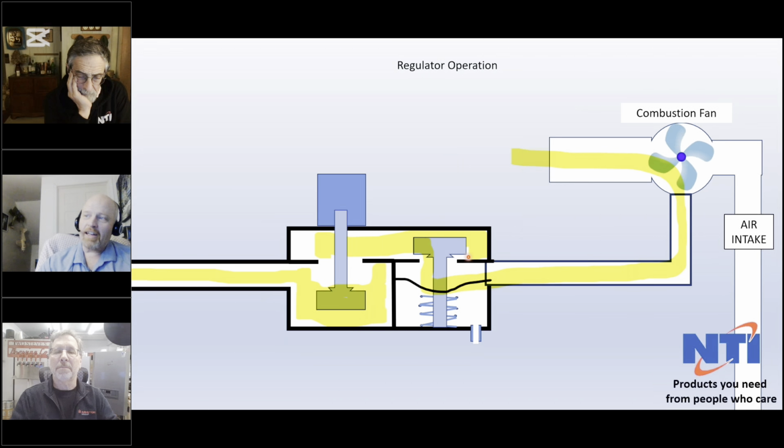topic. Again, our valve opens. And in a perfect world, what you're doing when you're setting the offset gas pressure, so you're going to make your adjustment to this regulator, you're tightening or releasing tension on this spring, you're allowing that spring to fine tune the gas pressure.